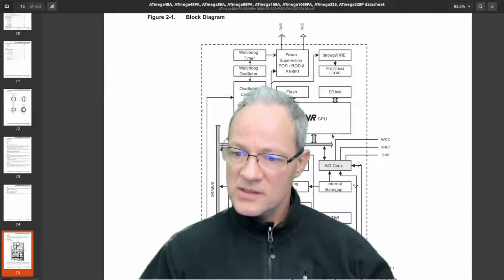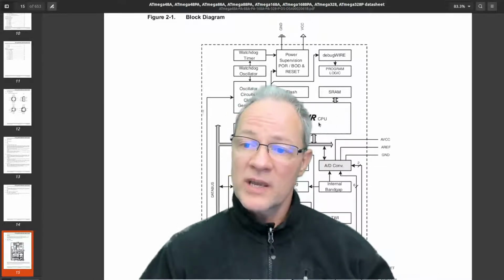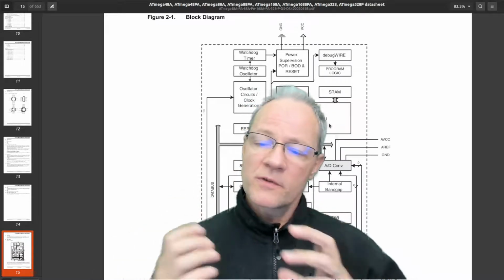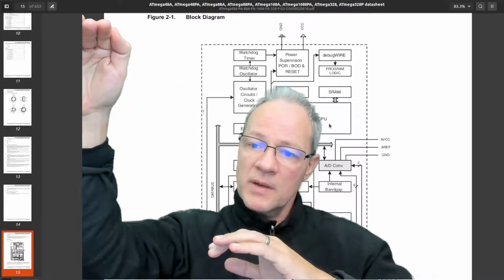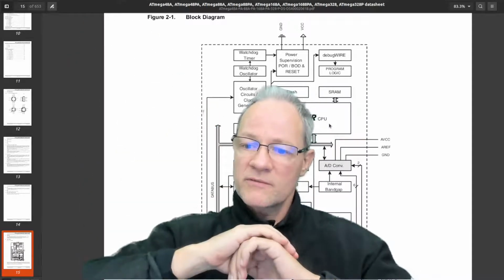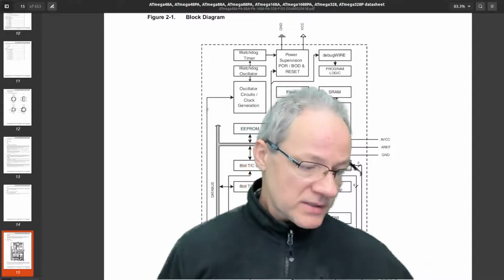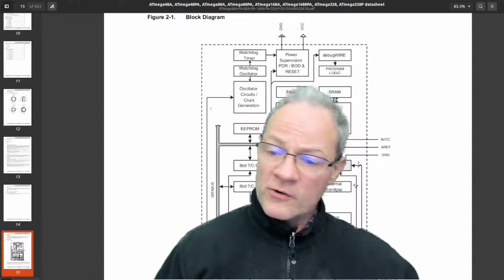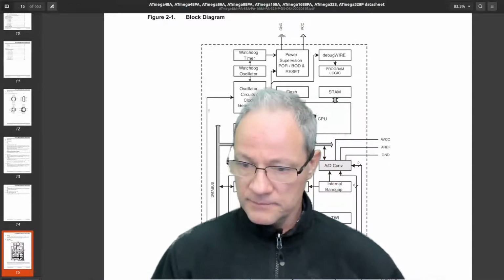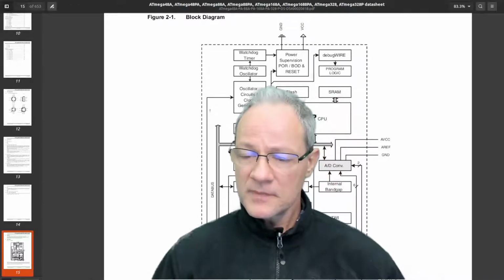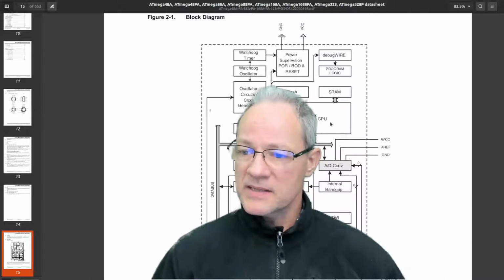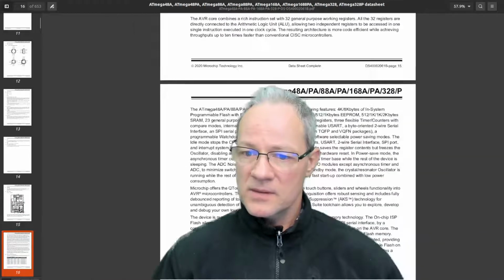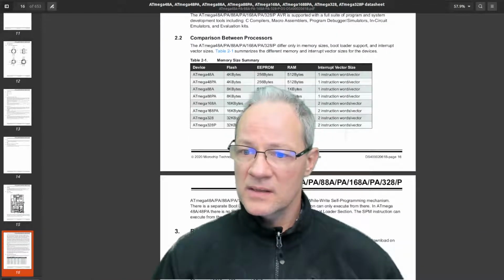And these registers will appear as locations in memory to that processor. So it's going to be as simple for your program to write to a certain address in the memory, so it will be written to that register. In some cases, there are special assembly commands for writing to those devices, to those registers. But in many cases, they are all memory mapped, so we can access them directly. All right, so let's see what else is there of importance.